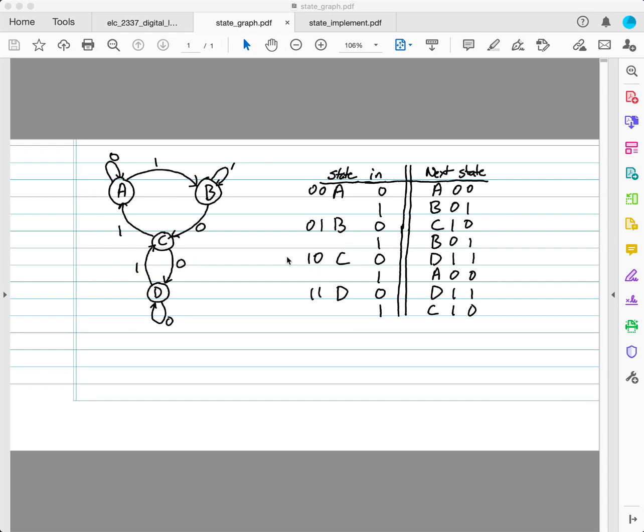So let's assume we go, now that we've shown we go from a graph to the state table, I'm going to assign state numbers now. That's why I just say, okay, A, B, C, D. I have no better reason to pick them. I look at the graph and I go, well, A, B, C, nice sequence of numbers. D's on its little side loop next to C. So I'm just going to number them in sequence. A gets 0, B is state 1, C is state 2, and D is state 3.